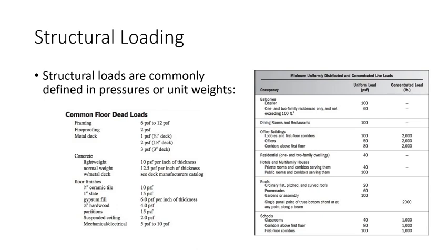There's two really good places to find that information. The first is standardized specifications like ASCE 7 or other international building codes. The other is the manufacturer. For example, whoever manufactured these drop ceiling tiles is going to specify their weight in terms of pounds per square foot.